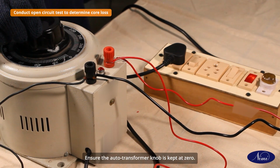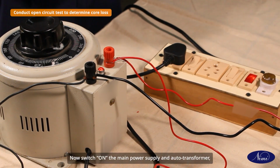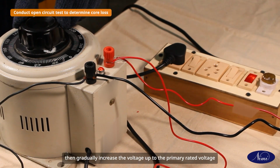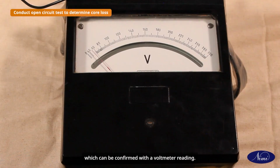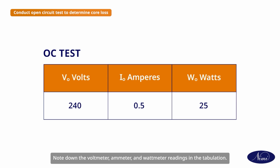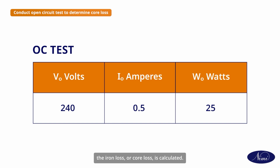Ensure the auto transformer knob is kept at 0. Now switch on the main power supply and auto transformer, then gradually increase the voltage up to the primary rated voltage, which can be confirmed with a voltmeter reading. Note down the voltmeter, ammeter and wattmeter readings in the tabulation. From the open circuit test, the iron loss or core loss is calculated.